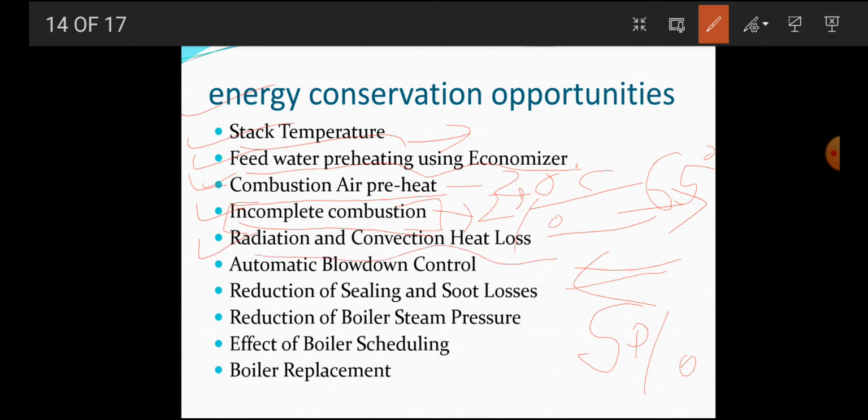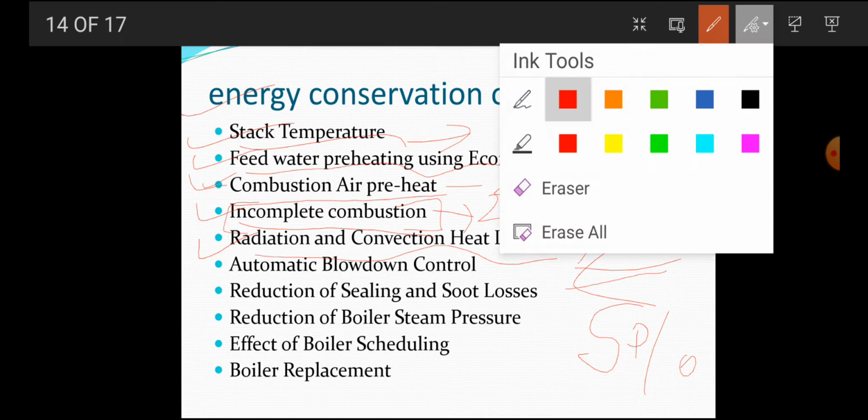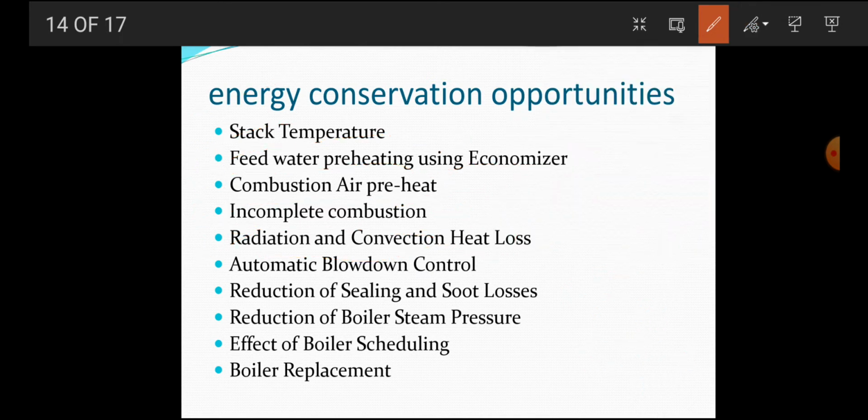The external surfaces of the shell boiler are hotter than the surroundings. So the surfaces lose heat to the surroundings depending on the surface area and the difference in temperature between the surface and surroundings. The heat loss from the boiler shell is normally a fixed energy loss irrespective of boiler output.